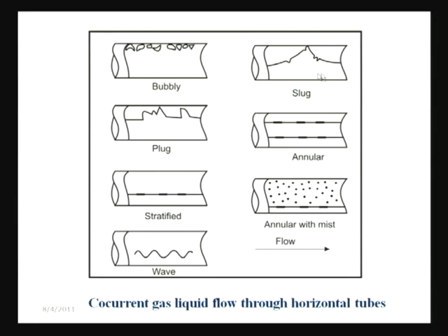So, this gives rise to the slug flow pattern as we have observed for the vertical case, but here definitely the slug flow pattern has an asymmetric character. Okay. Bubbly flow, which we had already observed there, annular flow, which we had already observed there. Generally churning is not very prominent, but churning can also be observed under these conditions. But all this bubbly, annular, slug, they are all characterized by one thing here, that is the asymmetry in the flow distribution, because the bubbles, the Taylor bubbles, as well as if you observe the liquid film in this particular case also, you will find the liquid film will be thicker at the lower side, it will be thinner at the upper side.